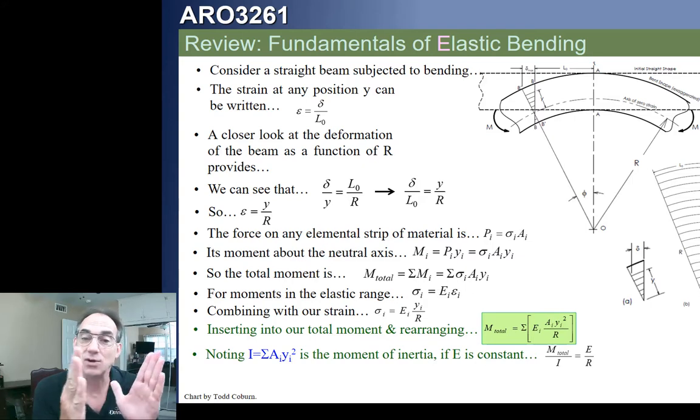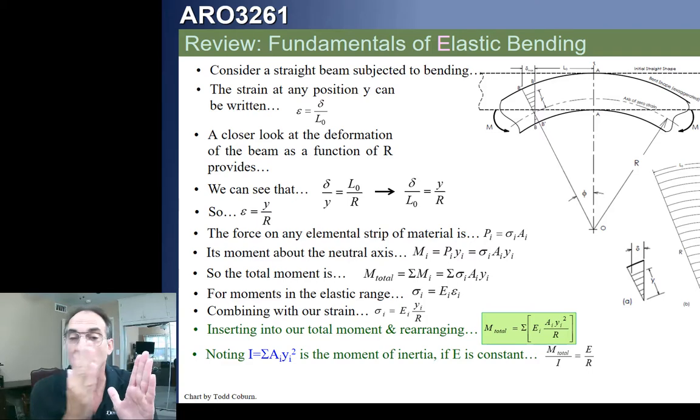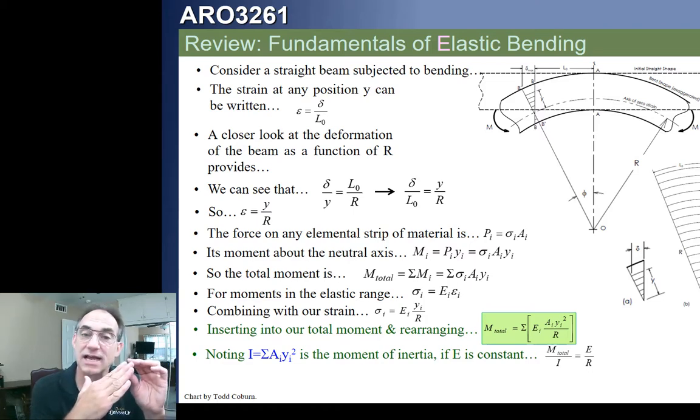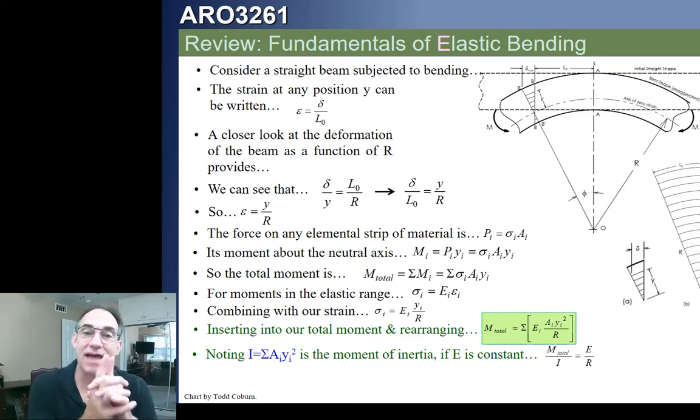So if we have an axial load, then if we exceed the yield, everything is exceeding the yield. We still have the same modulus across the entire section, even though it's changed from what it was. If we have bending, then the extreme fibers where the stress is highest will tend to deform, and that means the modulus will change as we go up the stress strain curve above FTY. And that makes it behave like it's a section made of multiple materials. In fact, that is the foundation of what we will study next semester in Aero 3271 when I teach you folks about plastic bending of sections.